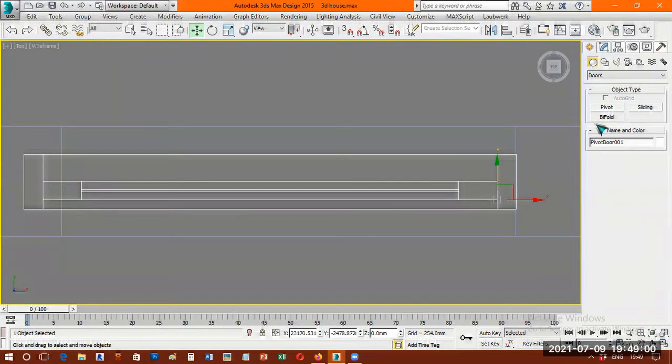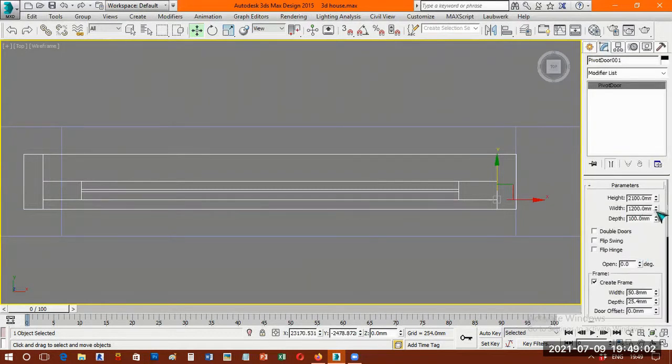So I go to modify. I slightly reduce the width size. You can see that the door is reducing or increasing based on my width dimension. Let me check. Because this door is considered including the frame width actually, not only the door plank. This dimension is considered including the frame dimension of the door too. So I have reset this to, let me say, 1100. Okay, done. Perfect match to this area now.